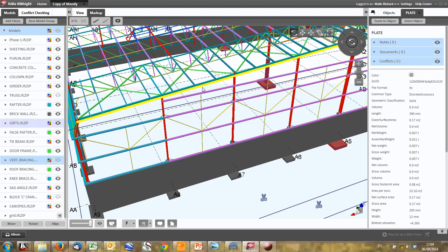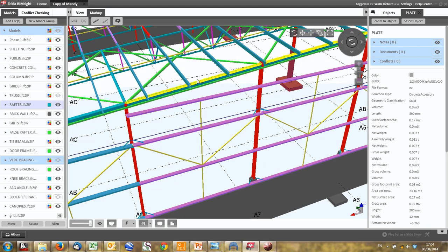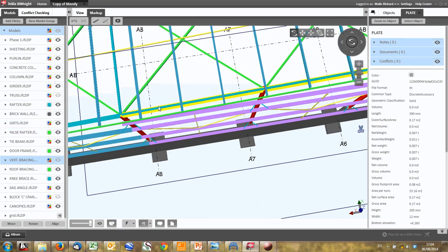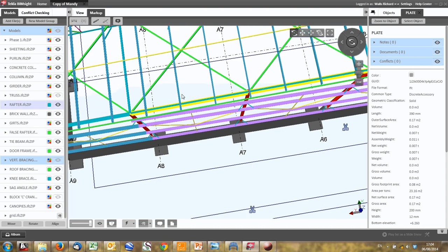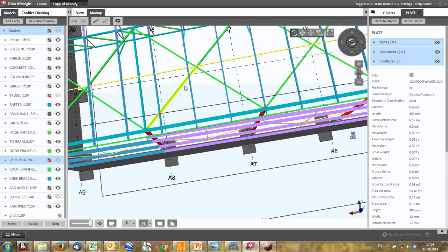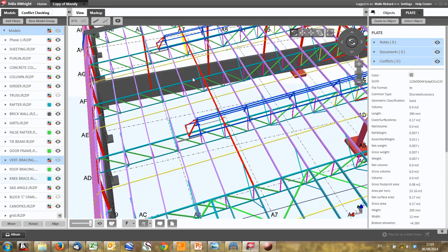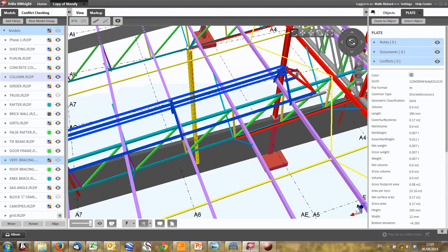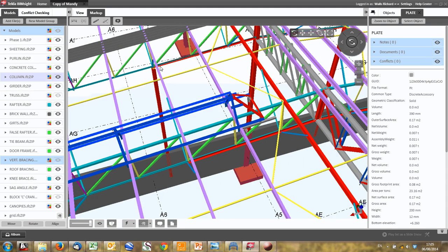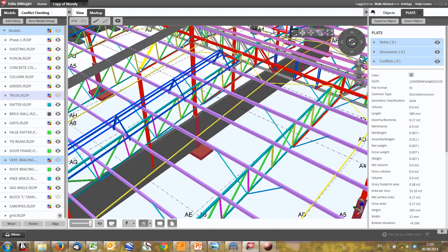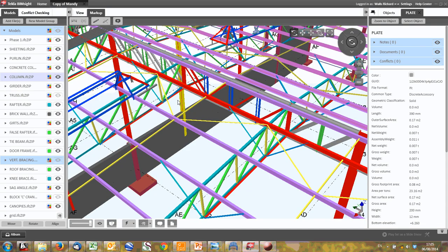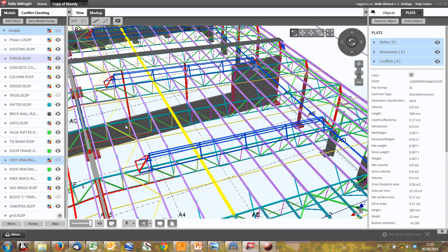Because imagine now if this gable column is in the middle. If this load pushes horizontally, where does it go? It doesn't have anywhere to go. So it just pushes and puts this beam into bending. So either you've got to design this beam for bending, or you've got to put something there to get the load across. In the middle, you'll see these ones carry almost no load. But even so, they fix the bottom of the truss, and we'd have to make sure that those little knee braces can carry any load that comes to them. Those are just temporarily in there, basically to support brickwork.